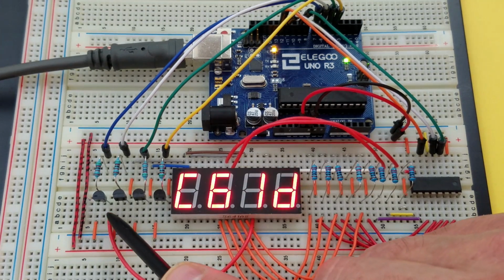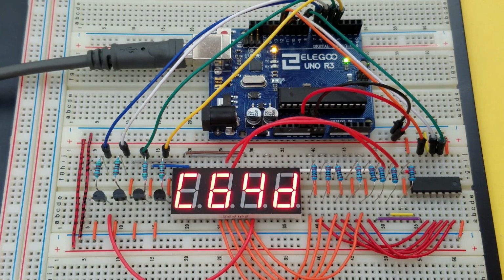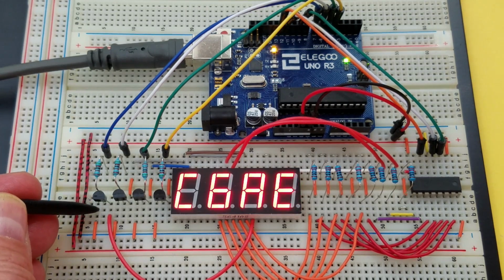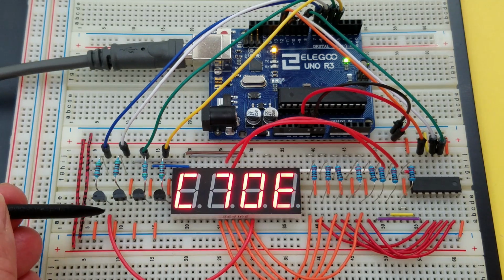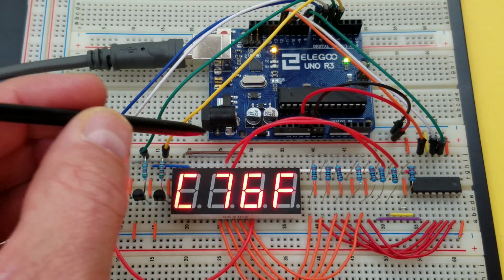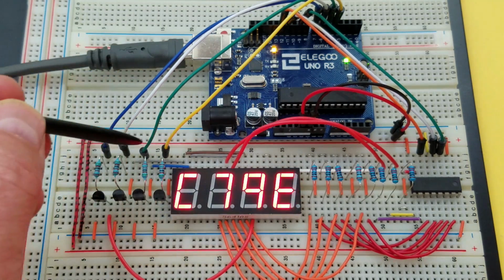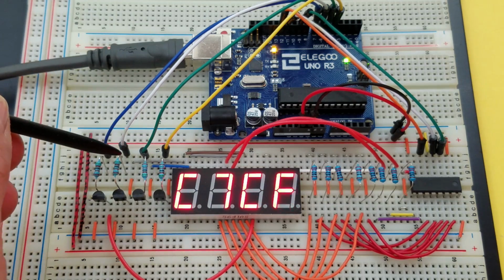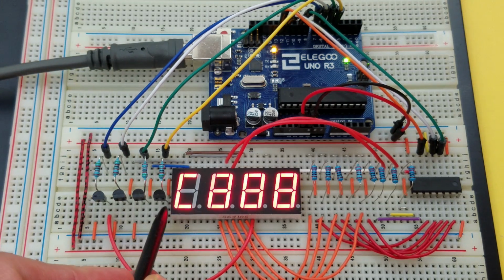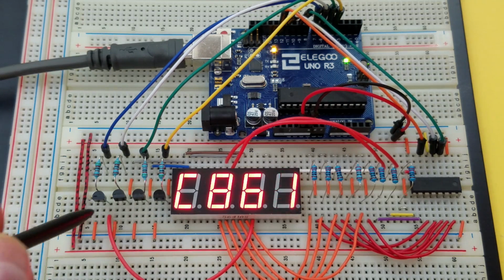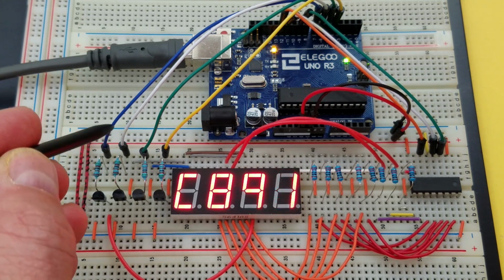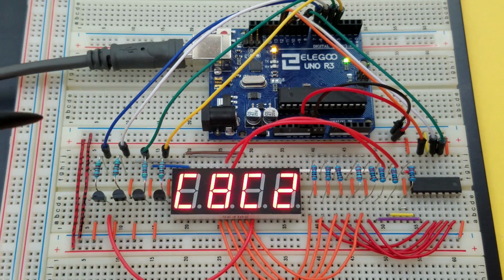Here we have the 3 connections to the transistor. We have the emitters that are going to ground. You can see that each one of these are going to ground. And the collectors, we have this one coming from D4, and the D3 and D2 and D1 are coming from above, going through the little jumpers right here, and then connecting to the collectors on the transistors. The base is then controlled by each of the Arduino pins here.